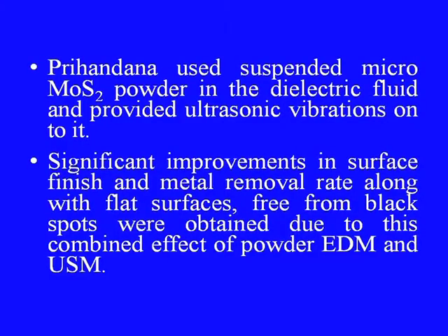Prihandana used suspended micro molybdenum sulfide powder in the dielectric fluid and provided ultrasonic vibrations onto it. So, these are different attempts by different researchers to make the ultrasonic machining and the electrical discharge machining processes work together in order to enhance their performance.